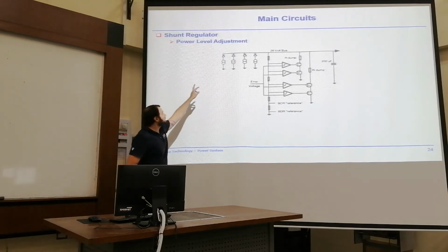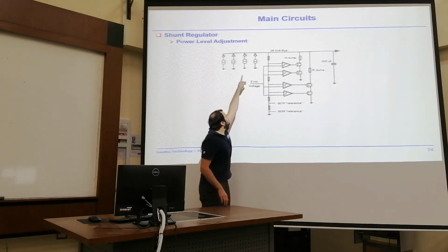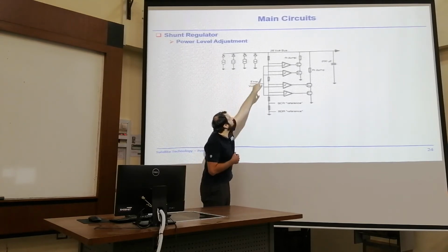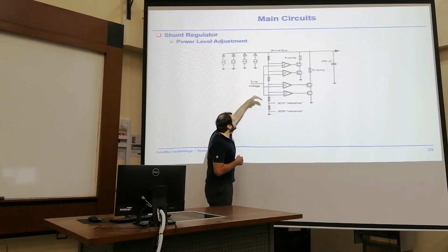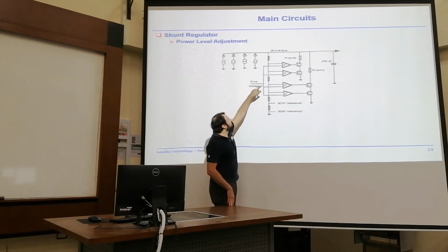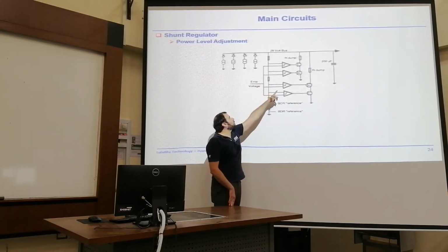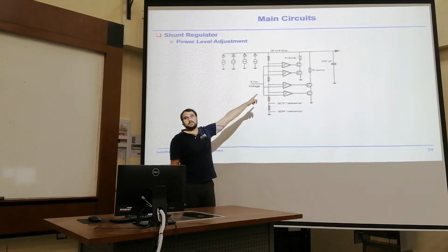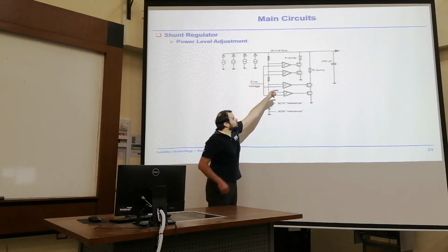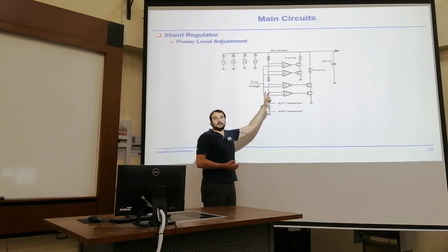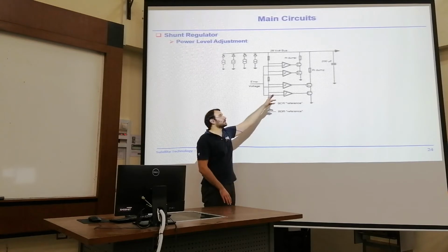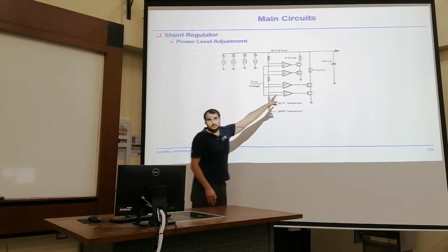You can see different power sources being fed in, again with a diode, and then by comparing the voltage of our bus with an error voltage or some reference voltages, we have some Schmitt triggers that could close some electronic switches, and you would dump your excess power over the shunt by closing that towards ground.